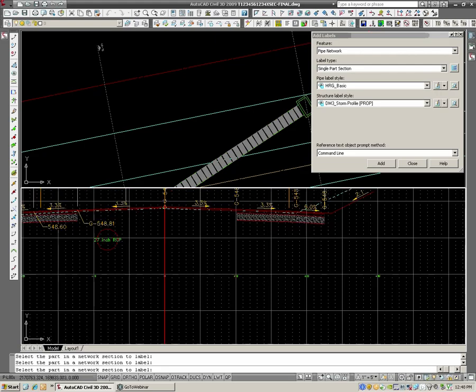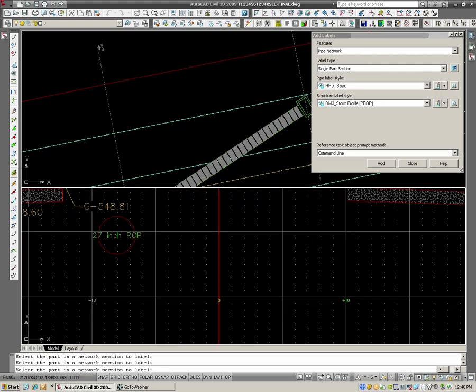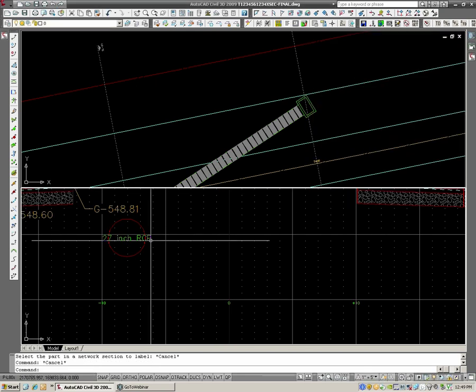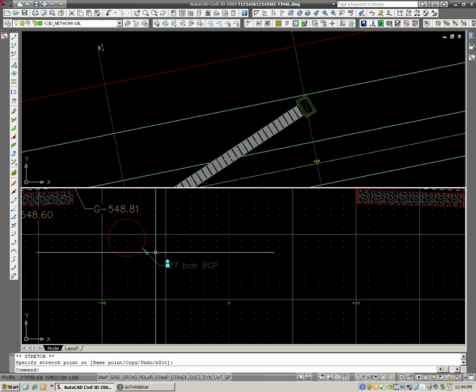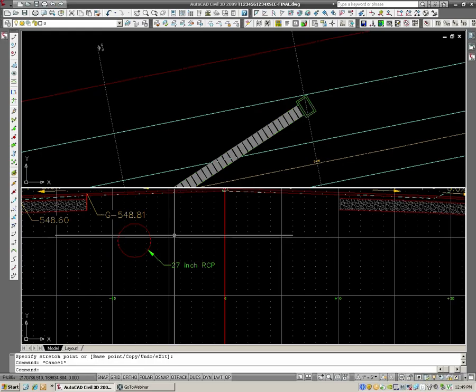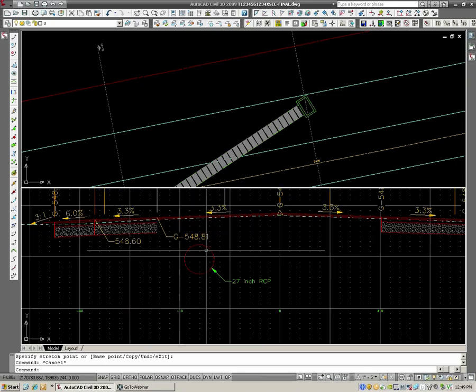I think we have one for pipes. Yeah, you know, we might need to beef up on our styles a little bit there. I think Josh Sadison's working on that right now, actually, getting these styles to show up a little bit better. Do know that, I don't know if we're doing something wrong, but we have had the pipes be a little skittish on us, act a little weird, show up or not show up. I think it was through a data reference. That's typically the trouble, is that you'll go into your cross-section drawing and all of a sudden these pipes won't show up.